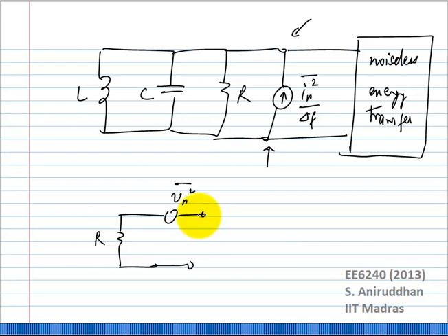It depends on what instant we are injecting the noise. Okay, that's right. But that is not what I am asking. If I just take any signal, so let us take a resistor, I have some Vn squared. What is Vn squared? 4kTR delta F. Correct? I know the noise of a resistor is 4kTR delta F. So if you had to figure out how much of this noise is in the amplitude and how much of this is in the phase.